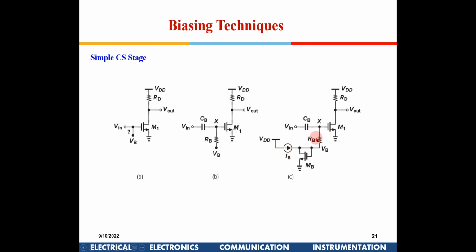This is the resistance network we have, right? So instead of that, we are giving a constant bias, a much better bias signal. It means that whatever you are giving down is a kind of DC signal. Yes. The Vin is AC, right? Correct. Vin is the AC signal. So generally, in a practical design, only one will be there. If you see the practical design, the gate will have only one connection. Yes. So how are we going to separate this, like a representation in reality?